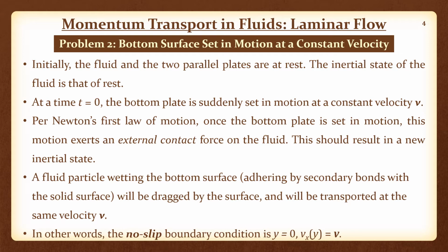Those bonds are more easily broken and reformed, and therefore there could be sliding or slip motion. One fluid particle can slide or slip past another, but a fluid particle that is wetting or adhering to a solid surface finds it more difficult to slip or slide past the solid surface.